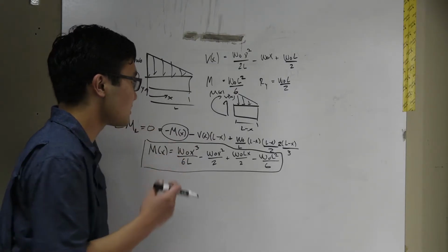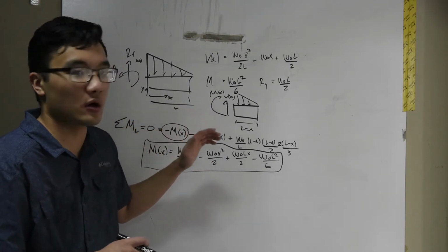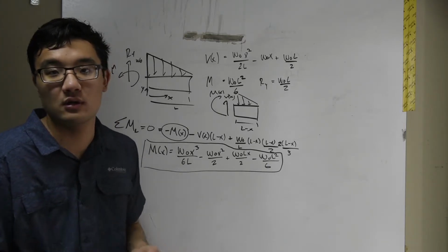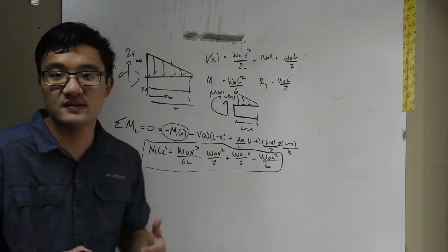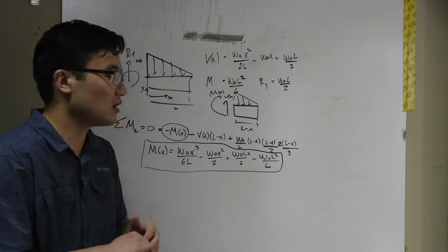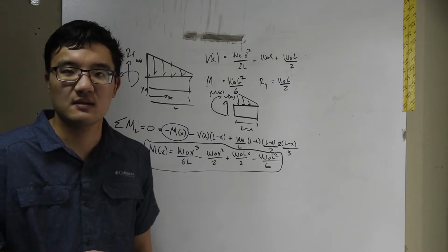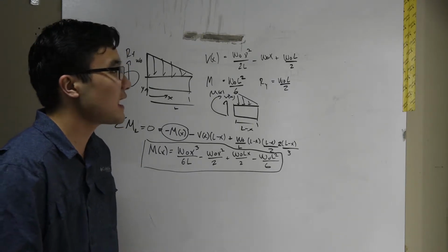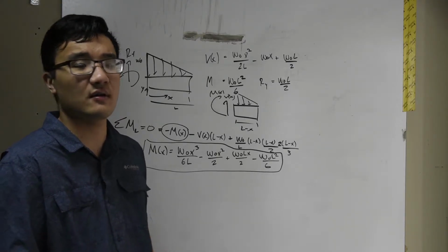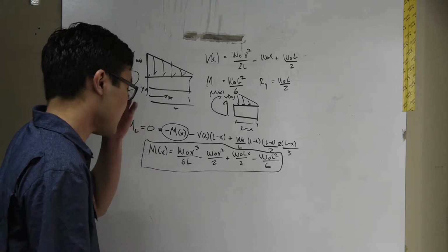And again, the way we solve this is by analytically determining what the loads were and how they created moments by point force analysis and centroidal analysis. All of the things that we've talked about, taking a distributed load into a point force, it all matters. That's the thing with structural engineering, all the concepts kind of build off of each other. You can't skip your fundamentals, which is why I think this lecture series is very important for all of you. So there we go. We've come up with an expression for moment.